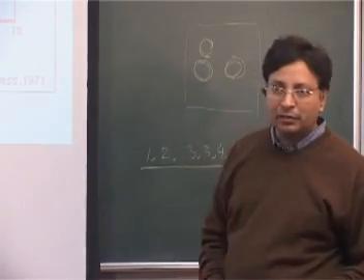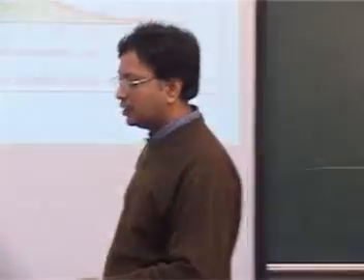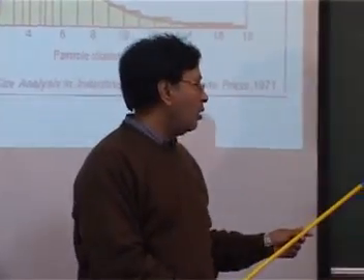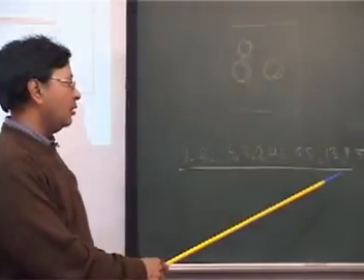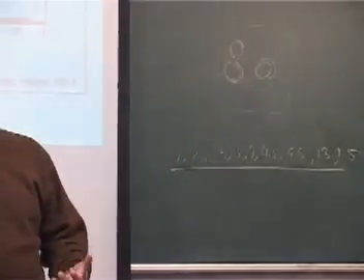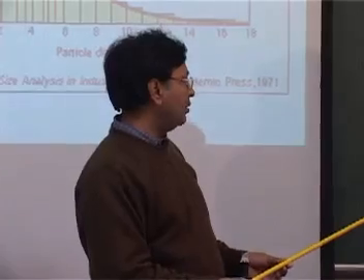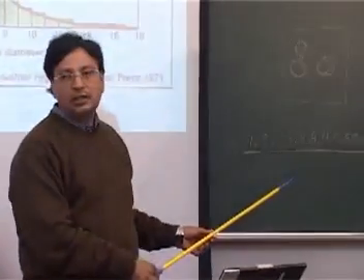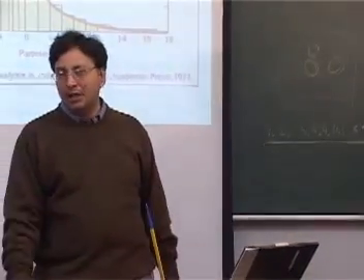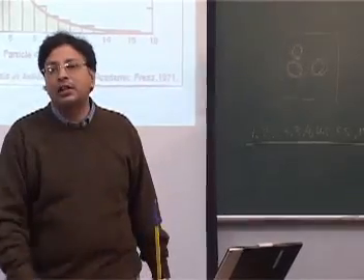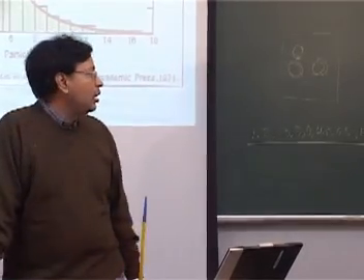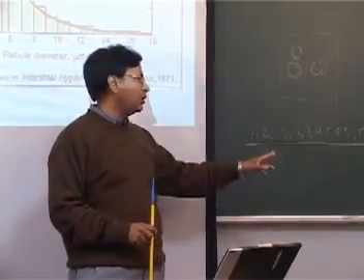You have to be a little careful sometimes. What you want to take is the median here, because you want to find out the average particle size. You have to be careful sometimes that in such a data set, you have to take the median, because that is a much more robust central point.